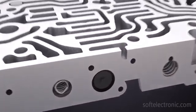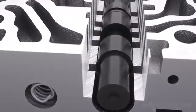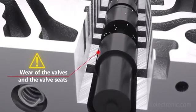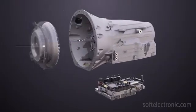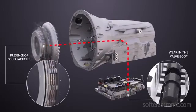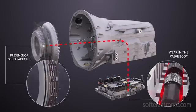The most common problem in the valve body is the appearance of gaps between the valve seats and the valves under normal wear. The presence of particles or elements not part of the composition of the transmission fluid can also lead to rapid wear. Defects in the mechatronic can also appear due to a problem in the automatic transmission in general. Until that issue is resolved, the mechatronic will continue to break down.